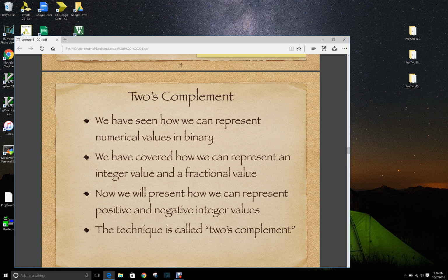We've just built a circuit that allows us to add 2 numbers together. And if you recall, subtraction of A minus B is really the same as A plus a minus B. So we're still going to use our basic adder, but instead what we're going to do is bring in a negative B when we want to perform the subtraction.